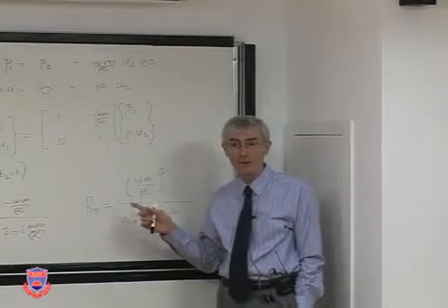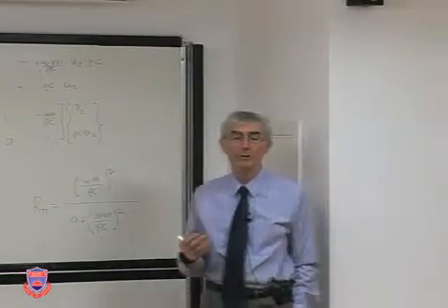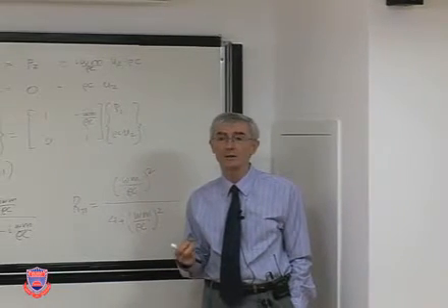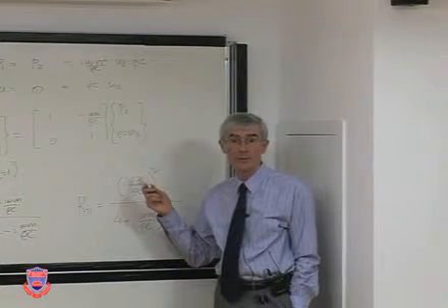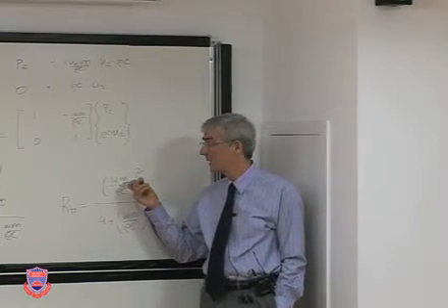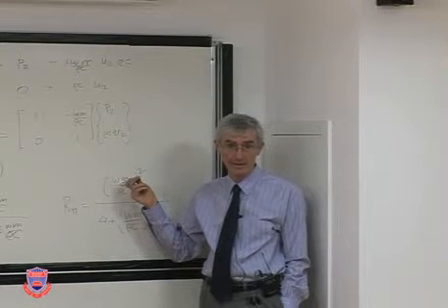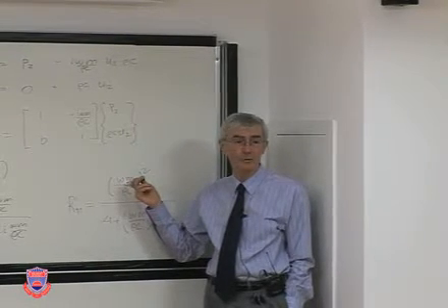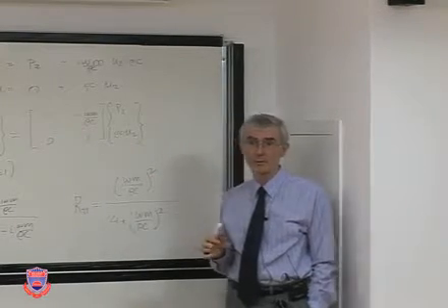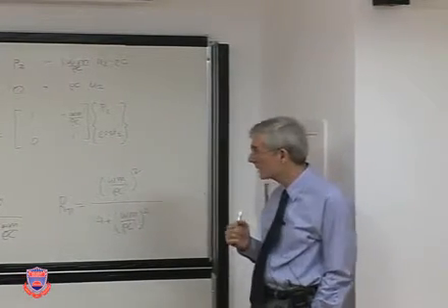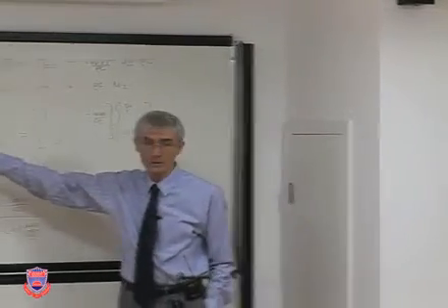That's very important. It's one of the fundamental issues in noise control. Low frequency sounds are very difficult to control. Therefore, for very low frequencies, the only thing you can do is increase the mass. For quiet rooms, very, very high values for mass. Secondly, let's go back to this impedance for a moment.